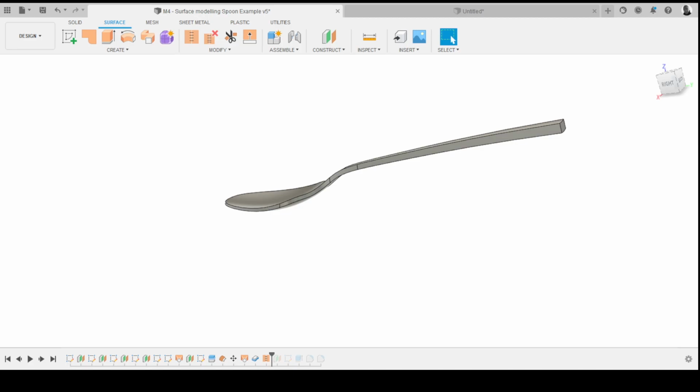I would like that spoon because I would like the bowl of the spoon to have a constant thickness, and then the starting of the thing, so I could make them 2 components. Yeah, so if you wanted to do that, how might you approach doing it, do you think? In terms of the solid surface modeling we've just done, what would you change to get to that? Rather than doing a move, if you're moving the whole thing parallel, what I do is I do one sketch for the top surface of the spoon, a different sketch for the bottom surface, and then do the cutouts for the whole spoon. Does that make sense?